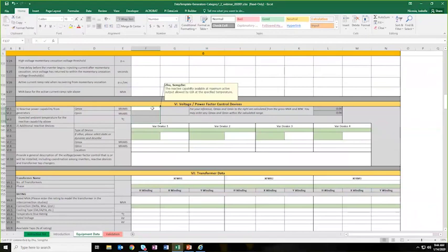Okay, so I'm trying to understand the Mod 25 test. Are you requiring the Mod 25 test to be done to actually verify what's in the GIA? Because often it's limited, and in the WEC requirement, if we are limited to some reactive capability and don't reach like 50%, we have to do another staged test in 5 years on the 5-year cycle for Mod 25. So I'm just trying to understand how you are enforcing that.